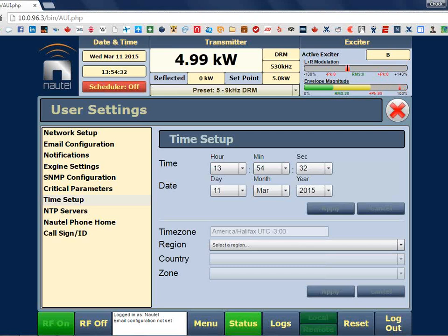Thank you for that. What's the lowest power level that the 10 kilowatt transmitter can run with good audio? We're working on characterizing that right now. I don't know exactly how low you can run it, but we expect to be able to reduce power at least to 10% and maybe down to 1% with reasonable audio. So you're working on that right now and doing the characterization. Yes. Okay. Network rotation chart. Yeah, that's on there. I believe you're talking about the Smith chart.